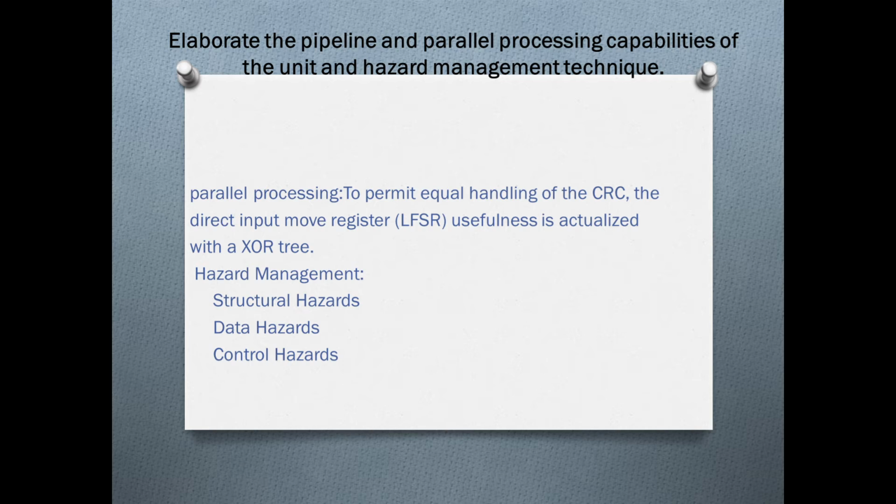This usage shows the identical behavior as the LFSR approach after 8 bits of data are shifted in when the LSB is shifted in first. The generation of a signature count must be started by writing a seed to the register to initialize the register.